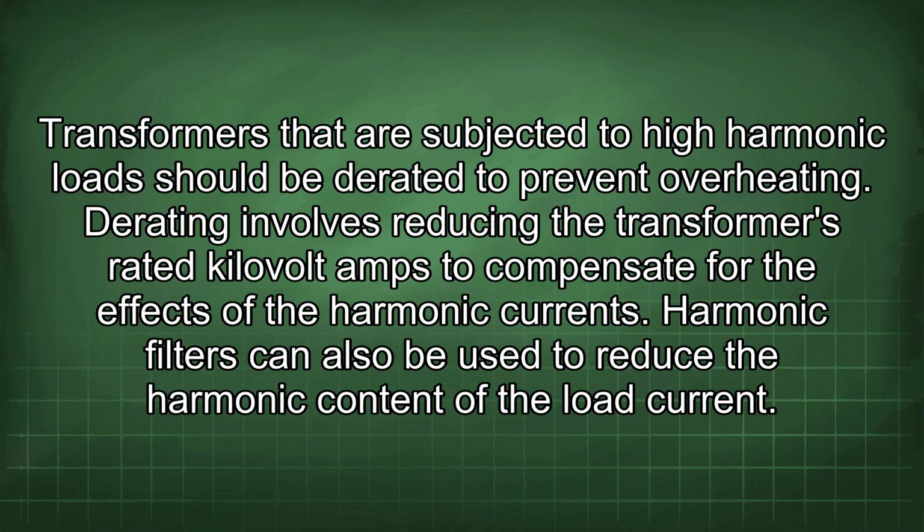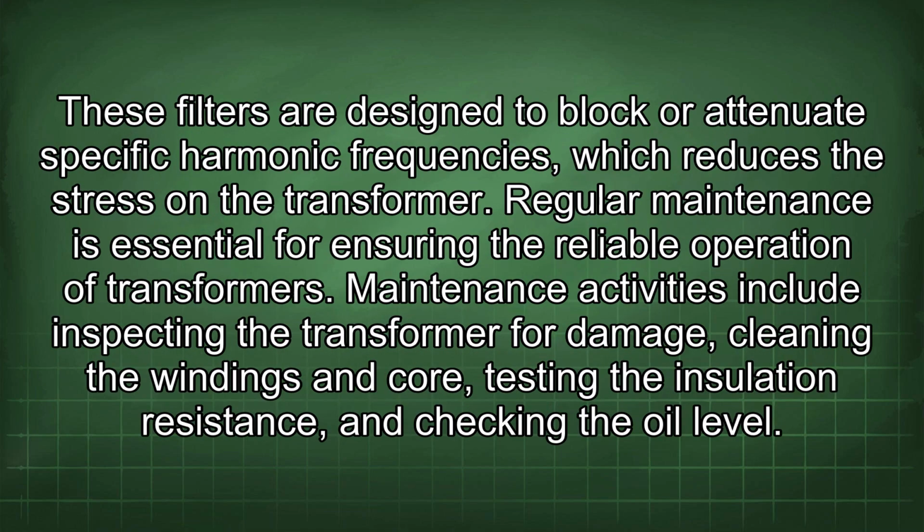Harmonic filters can also be used to reduce the harmonic content of the load current. These filters are designed to block or attenuate specific harmonic frequencies, which reduces the stress on the transformer. Regular maintenance is essential for ensuring the reliable operation of transformers. Maintenance activities include inspecting the transformer for damage, cleaning the windings and core, testing the insulation resistance, and checking the oil level.